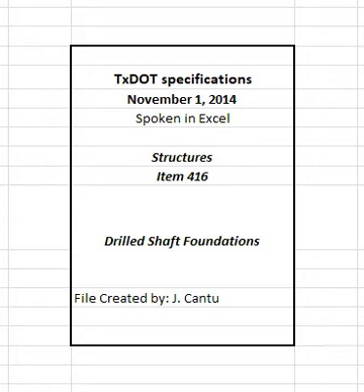If this condition exists, notify the engineer and note the elevation and circumstances related to the loss of seal on the drilled shaft log. The elapsed time from the mixing of the first concrete placed until the completion of concrete placement, including extraction of the casing, must not exceed the time for which the concrete maintains a slump of over 4 inches in accordance with Article 416.2, Materials. Modify the concrete mix, the construction procedures, or both for subsequent shafts if the elapsed time is exceeded.